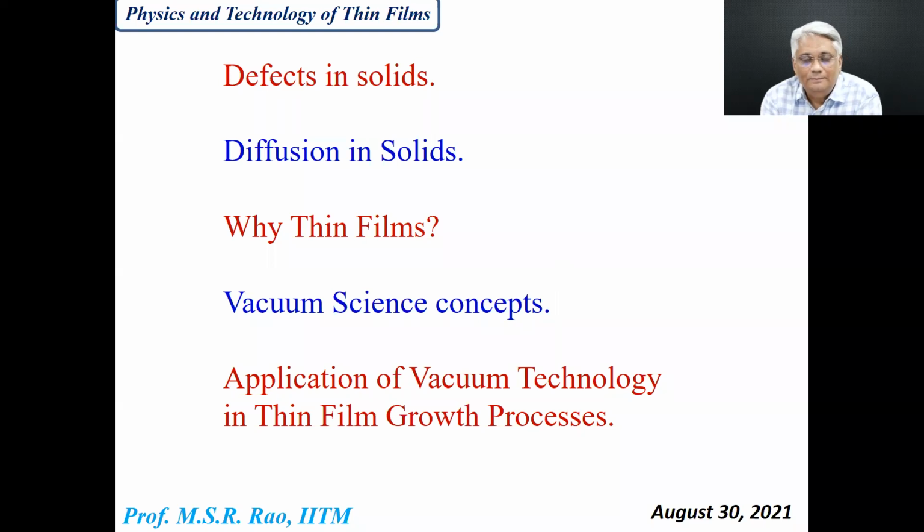It's a big challenge to get 500 degrees centigrade in a furnace, 1000 degrees centigrade, then 1500 degrees centigrade, and 2000 degrees centigrade and above becomes much more challenging. So high temperature is also required for thin film growth. For thermal evaporation of bulk components, you need to vaporize the material by taking it to its melting point. So high temperature is obviously required.